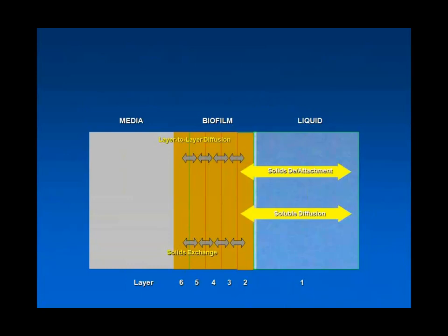So what this then leaves us with is the image that I showed you earlier here, where we have all of these processes going on, and we are now modeling the concentration in each one of these biofilm layers. So these are treated somewhat like little completely mixed tanks in series that are connected hydraulically through all of these different processes. And then we convert them through a calculation where we convert the concentration to a thickness via the density and dry materials content of that biofilm. Those are parameters that you can adjust in the model. However, we generally find that the default values are fine.